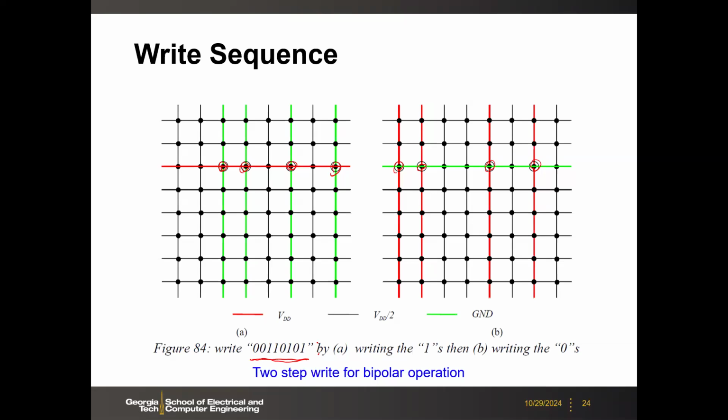So this is like opposite to what we do in NAND flash. In NAND flash, we do a first erase operation and then we program the page. So okay, that's a good question. In NAND, because of the organization, we always erase the entire block, and then we program page by page or row by row, right? So here actually you have different options. What I described here is this 2-step, where you write ones and write zeros, because here you can do random kind of access.